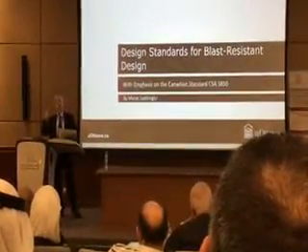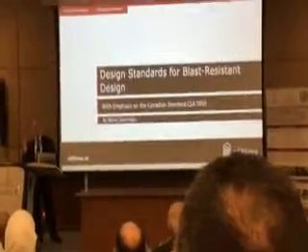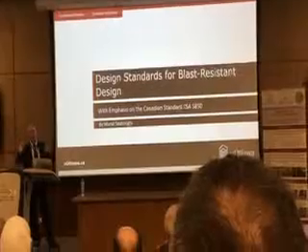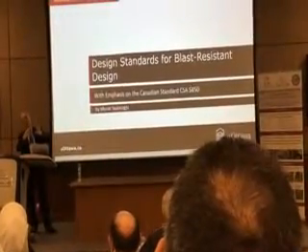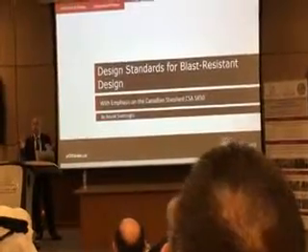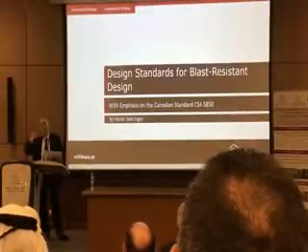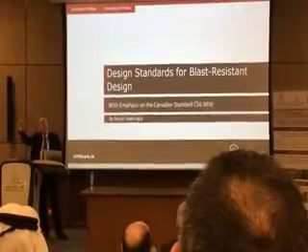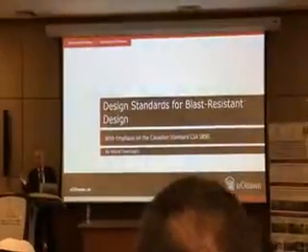The rear wall is usually not done unless you have a good reason, because it helps you, right? You push the structure that way and the rear pressure is acting in the other direction, helping you. And by the time the shock wave travels past the building all the way to the back of the building, the magnitude diminishes quite significantly.